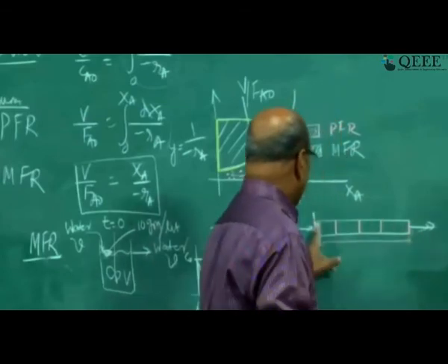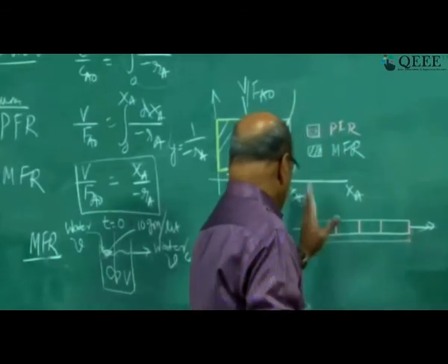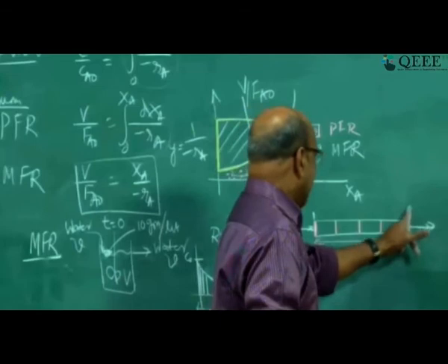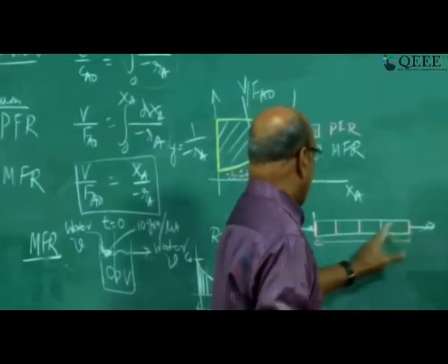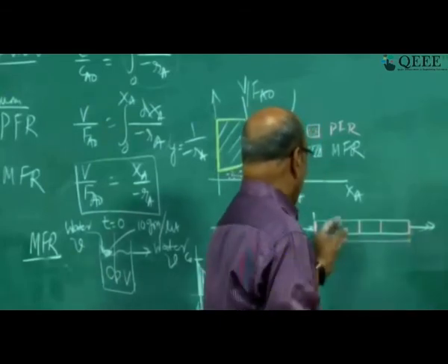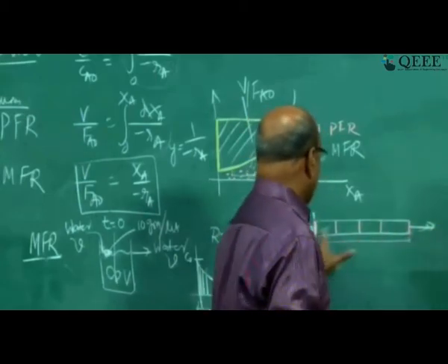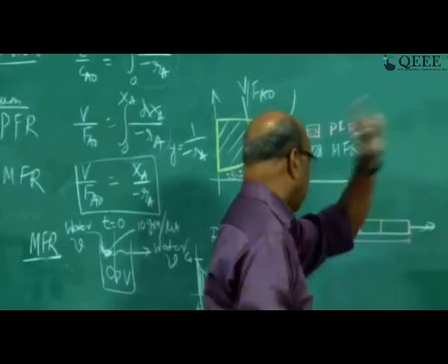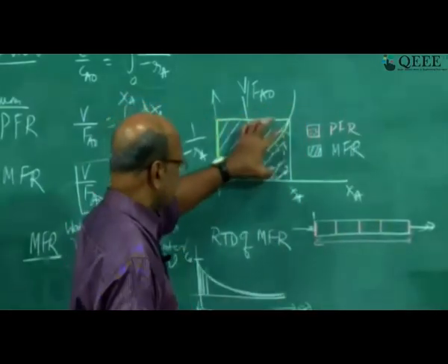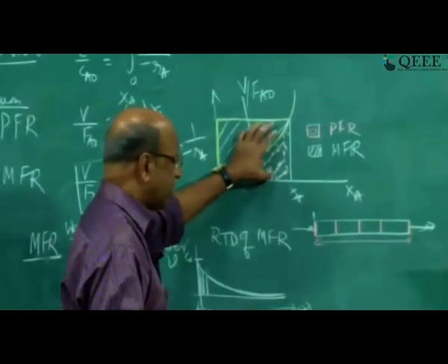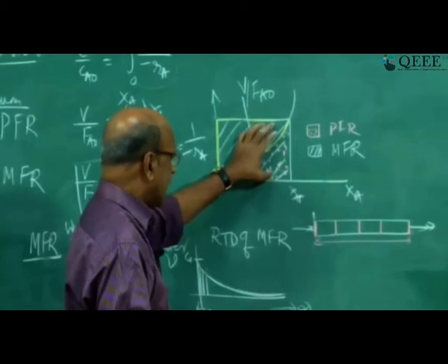So now conversion in each and every particle of this disk is the same, and the average is exactly the same, and we are not losing any molecules, earlier coming or late coming and all that. That is why you get the maximum conversion in a plug flow reactor. That is the meaning of this graph. I don't know how much you could catch, but I think you need some thinking about this.